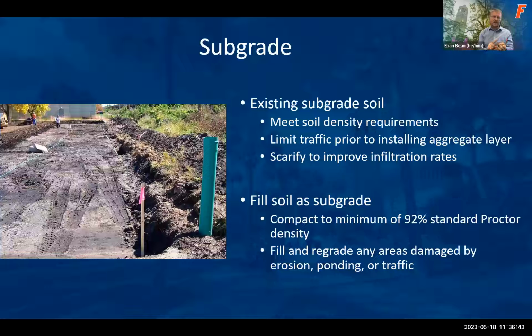Once the aggregate layer, the reservoir, the choker course, or the bedding layer is put in, we want to make sure that there is no traffic. I'm sorry. We want to make sure there's no traffic until those layers are put in, because any vehicle traffic over that exposed subgrade could further compact that subsoil.